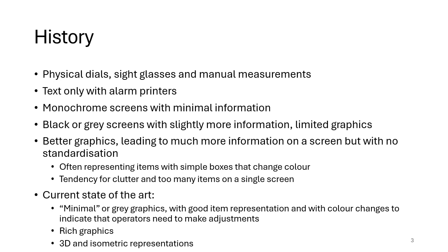So you might see a large P&ID from a process plant, which might be an A0 piece of paper when it's developed, and that could be crammed into a single screen of relatively small size, so you'd get a lot of valves and pipes, a lot of different colors, and a lot of different measurements, and that could make it very difficult for the operator as well. Again, training helps and operators can get used to this clutter, but it makes it very unattractive for new users, and the possibility of making mistakes is also quite high.